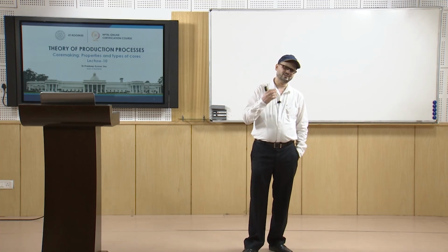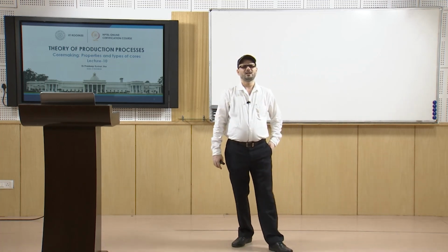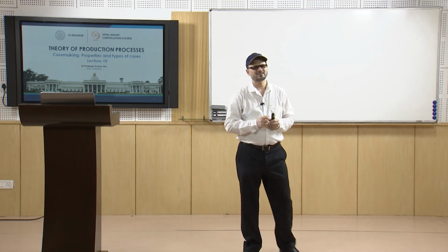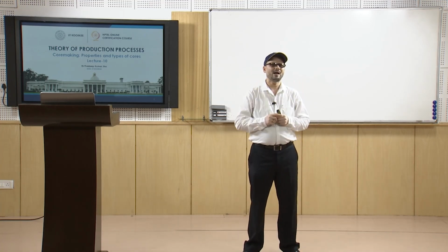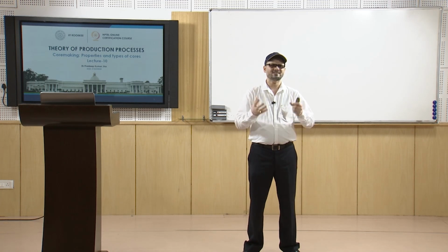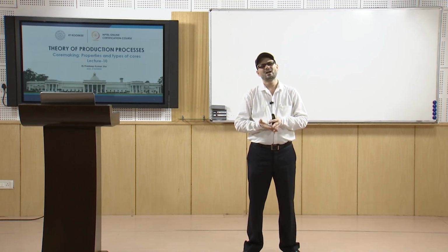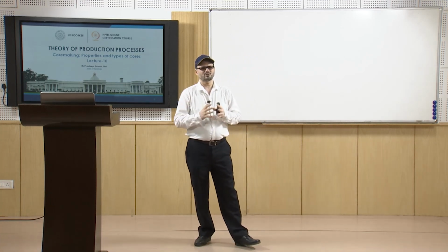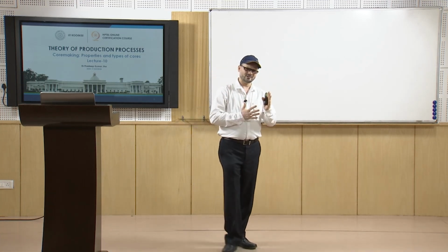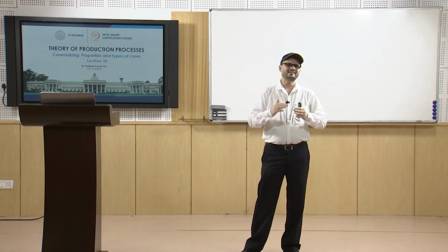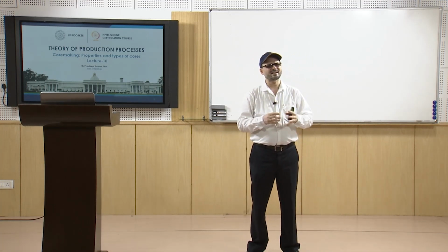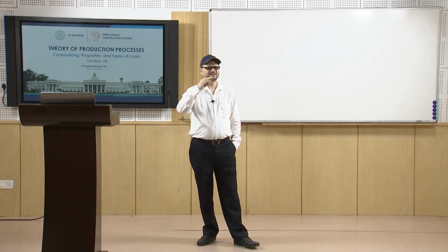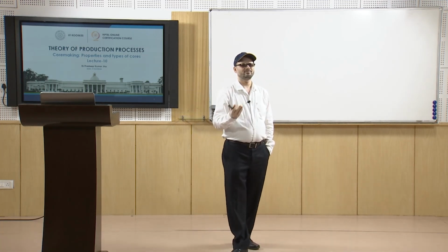Otherwise, if it gets stuck or sticks to the cast surface and you have to hammer it hard, or it does not have proper collapsibility during the casting solidification itself, it can create tearing kind of phenomena. So, core knockout is done basically at the end of solidification.